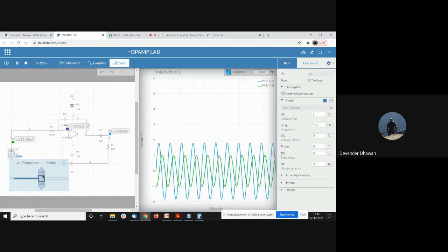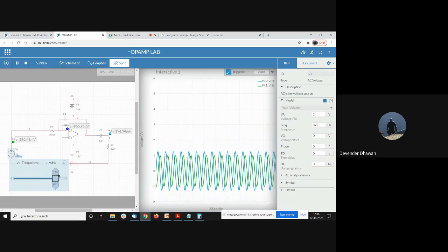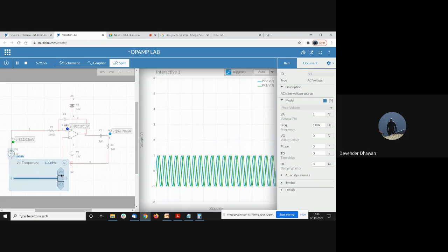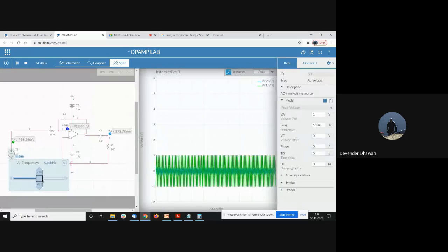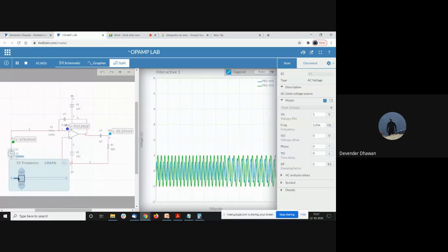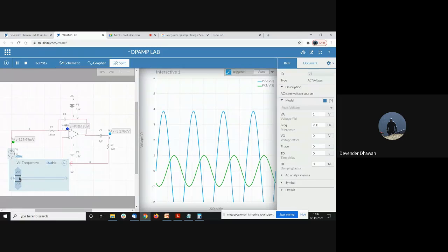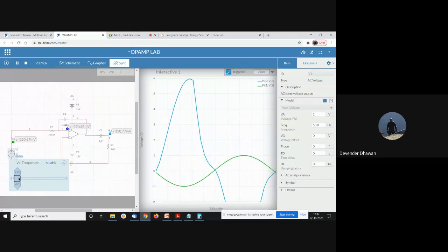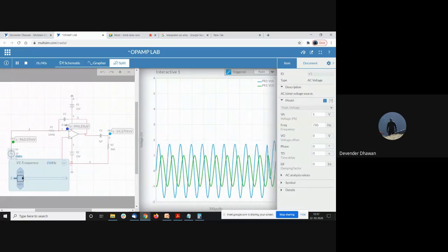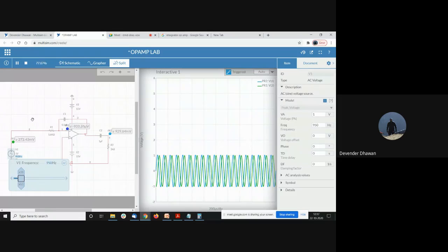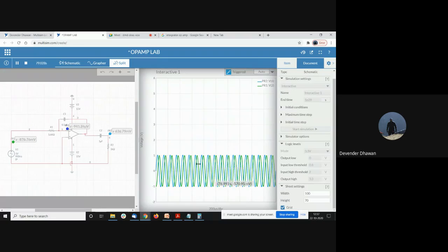Now the gain has started decreasing, and around 1k we saw that it was almost equal. After that it will start decreasing. So the frequency response, the bandwidth also we can check using AC sweep. The gain is maximum in this particular part, the 100 to 500, 600 range. At 1k it is almost equal to our input.